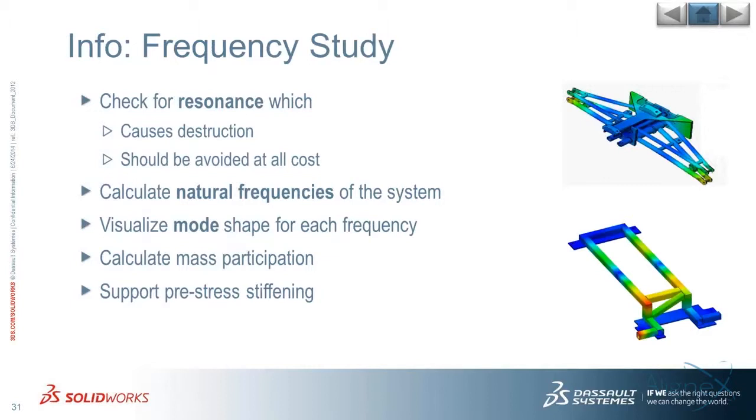So with our frequency study, we can calculate these natural frequencies of our system and also visualize the mode shapes for the frequency. The important takeaway with a frequency study is, if you have some data of what the load inputs are going to be, for example, driving through a dirt field or driving over the highway, there's generally a lot of information out there on load inputs and frequencies that you want to avoid when designing for those environments.